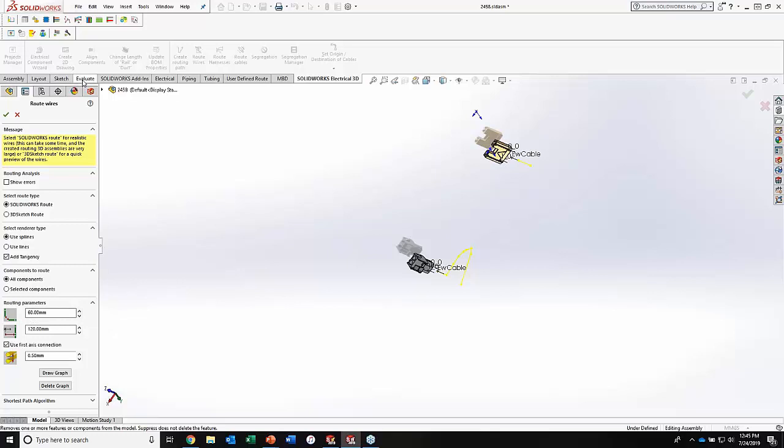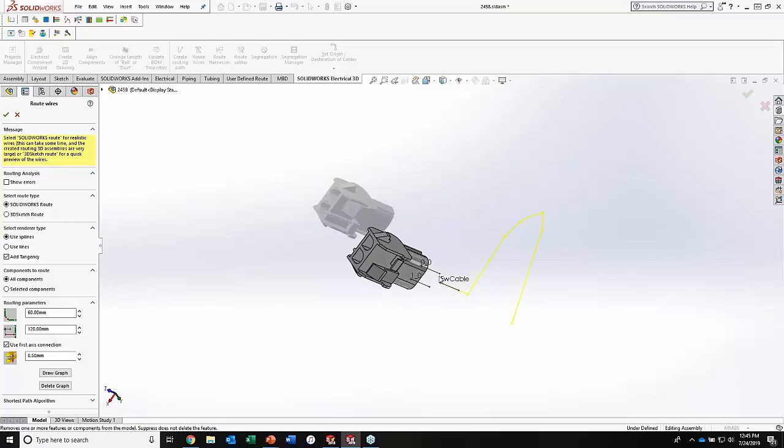Remember that under your evaluate, you have a distance or a measure command that you can use to find out what these different distances are. The second one that you have to be very critical of is this distance in between the first point, the connection point of your component, so from here to the first EW path.